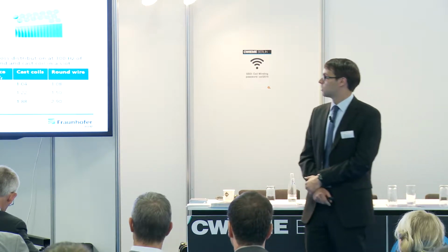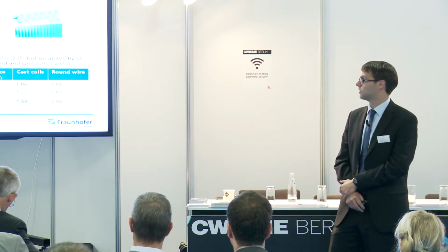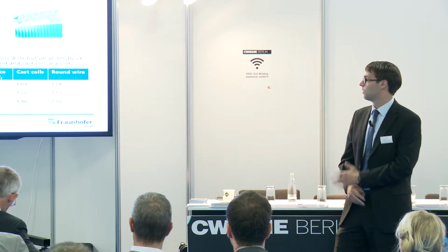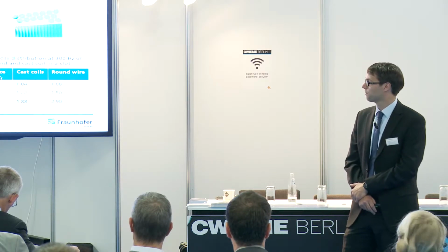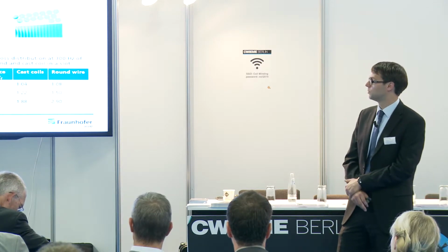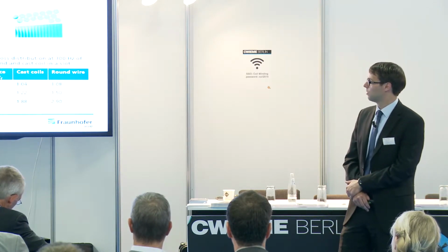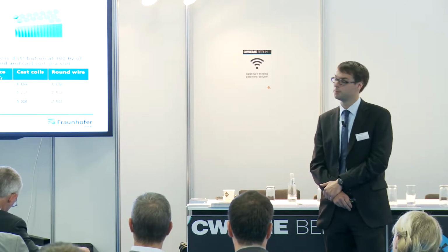From an electromagnetical point of view, of course, the biggest advantage is the slot filling factor. We have a reduced resistance compared to a wound coil with same outer dimensions. So we can use this to reduce the slot height of the machine, to reduce machine weight and material costs. Furthermore, the flat conductor arrangement leads to reduced current displacement effects.